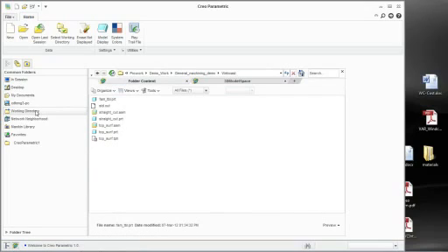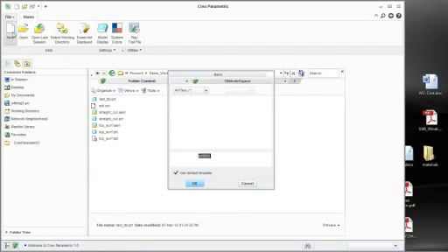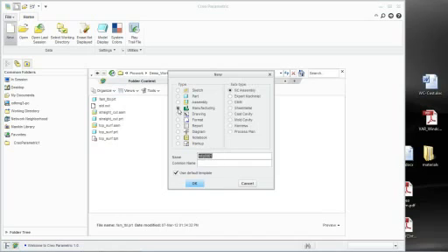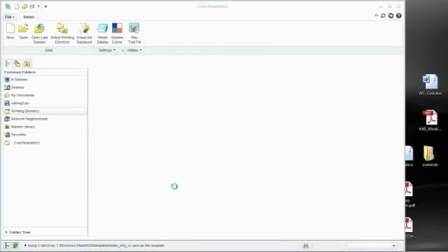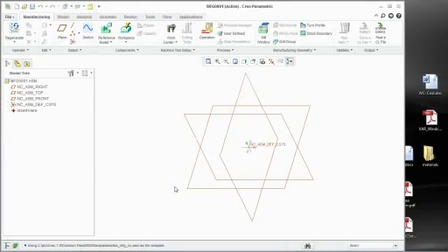Now, a lot of times when you go into customers, or at least when I go into customers, and they haven't had a whole bunch of guidance on how to start it up and get things going, is that for those of you that are using software, when you say File New and you do hit the manufacturing button, and I have to do this because mine's set up a specific way, is that when you start a toolpath file, an actual toolpath assembly, essentially what you have here is really just an assembly with manufacturing ideas on top of it, okay? And what you have to create is this manufacturing environment to start out with.